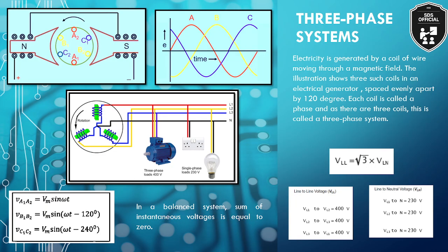So the question might come into your mind, from where does the three-phase supply come? This happens on the generation side. Whenever three-phase generators are used, three-phase induction or three-phase synchronous generators, the supply is obtained in the form of three-phase supply, which is displaced from each other by an angle of, or you can say the angular difference between these three supplies would be 120 degree. These are equally apart. Now why does this happen?